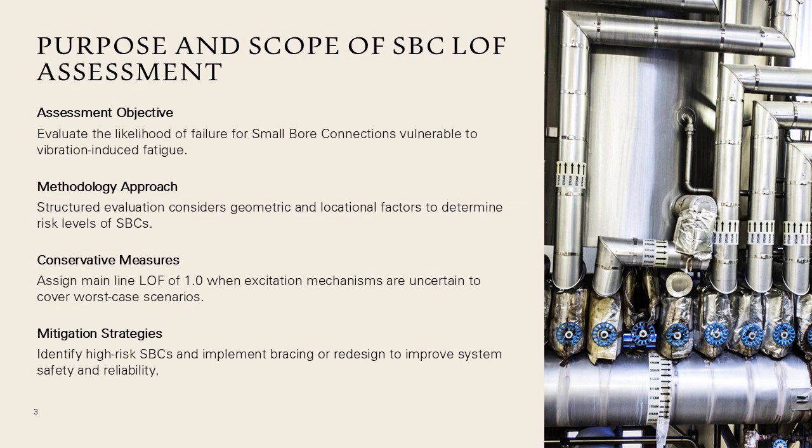If uncertainty exists regarding excitation mechanisms such as slug flow or environmental loading, a conservative approach is recommended by assigning a mainline LOF of 1.0. This ensures that the SBC assessment accounts for worst-case scenarios. The process also emphasizes the importance of avoiding coupling between SBC natural frequencies and tonal excitation frequencies, which can amplify vibration effects. Ultimately, the goal is to identify high-risk SBCs and implement mitigation measures, such as bracing or redesign, to enhance system reliability and safety.